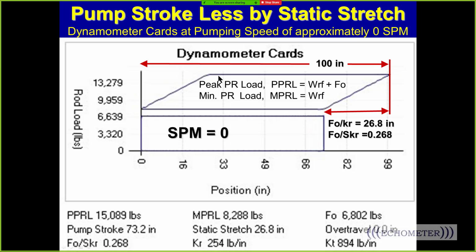Now, if we increase the speed, something happens. As we increase the speed, we start to see a peak load here and a minimum load there. Why? Because of the acceleration force created by pumping faster than 0 strokes per minute.